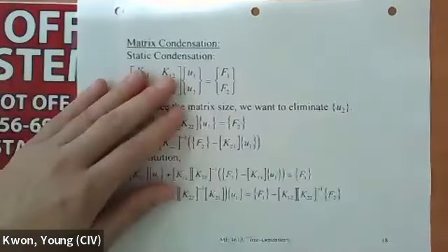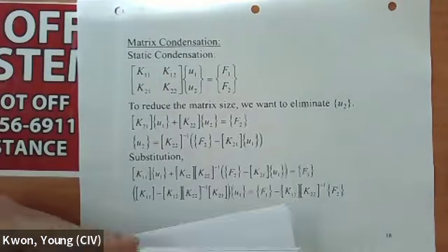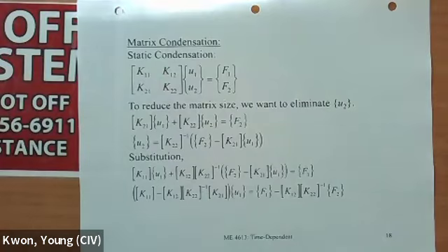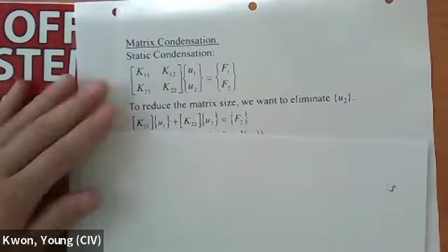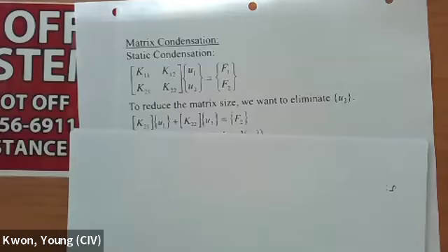In mechanical engineering, there are generally three types of eigenvalue problem. One is what we talk about here: vibration is a typical eigenvalue problem. Another is buckling of a column, which is also an eigenvalue problem. And the third one, if you go into a little more advanced class, is principal stress.